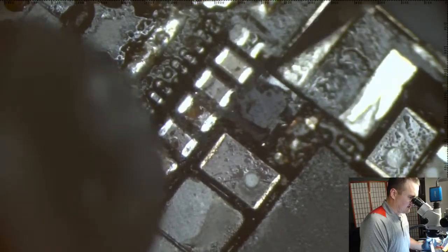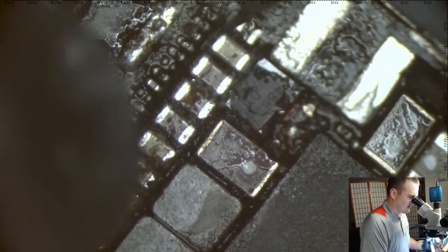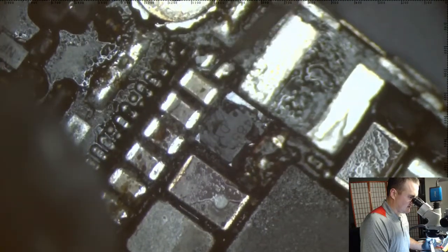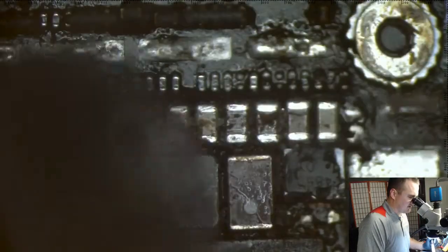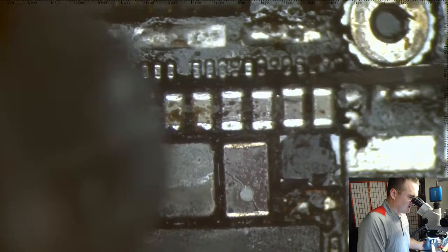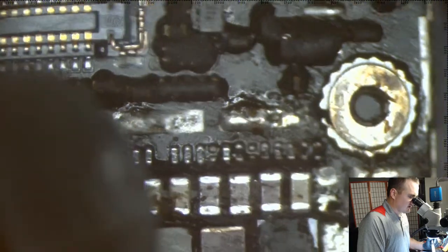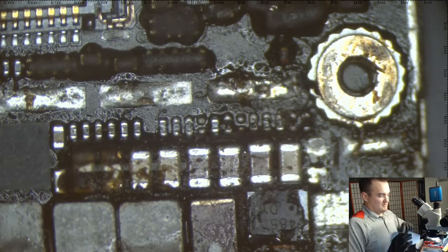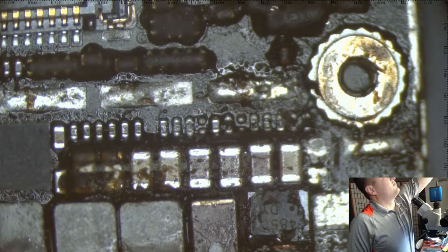Still have plenty to learn on. That's what I would recommend if you're just getting into micro-soldering. Find yourself some dead boards. If you need to buy some, people sell them. They're out there. Get you some water damage boards, get you some no power boards. I mean, people sell iCloud locked boards because you can't do anything with them unless you're doing something really dishonest.